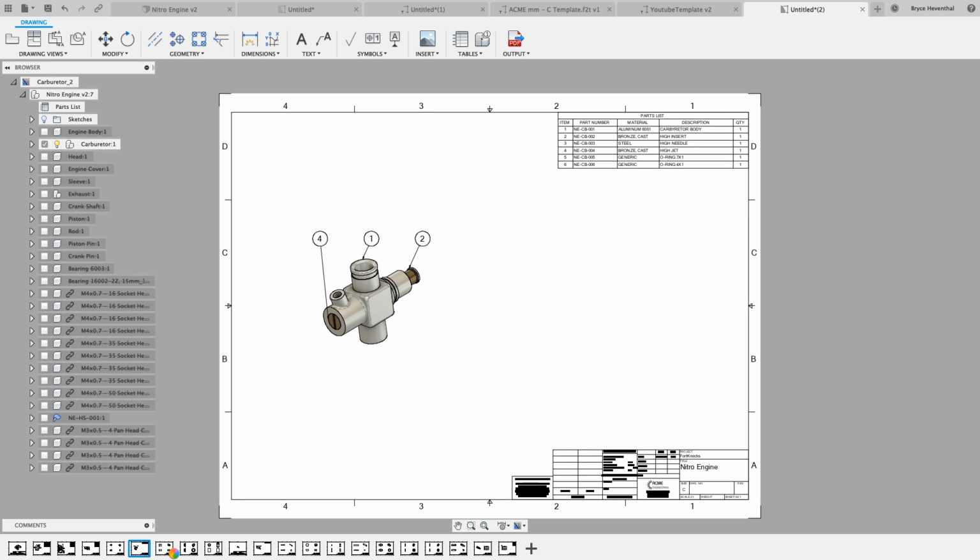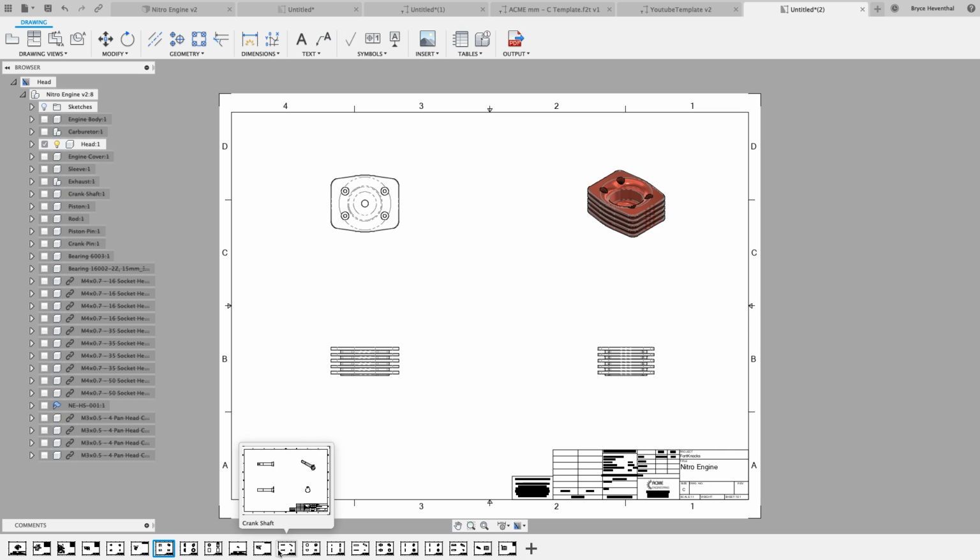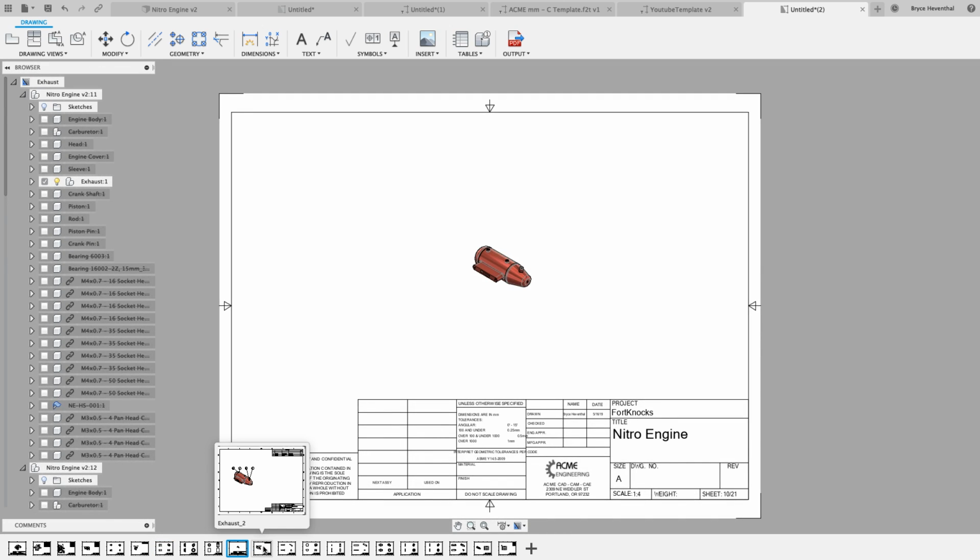And then you could go through and see your parts, and you'll see that it created quite a few sheets for the parts, as well as the sub-assemblies. And you get little previews as you hover over. And at any time, because as it goes down, it builds it one by one by one by one, maybe you wanted all your sub-assemblies up front. So, for example, this is a sub-assembly. I could just grab these two drawings. I can't do them at the same time, but drag it all the way to the front if I needed to reorder my drawings.